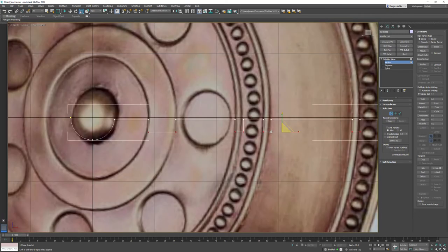And then all I'm doing is I'm in scale, and I'm just dragging down that Y button. But you can only do that when you have selection center. If you only have it on point center, nothing's going to change. All right, let's switch. We'll go to move, we'll raise those up so that they're slightly raised above.